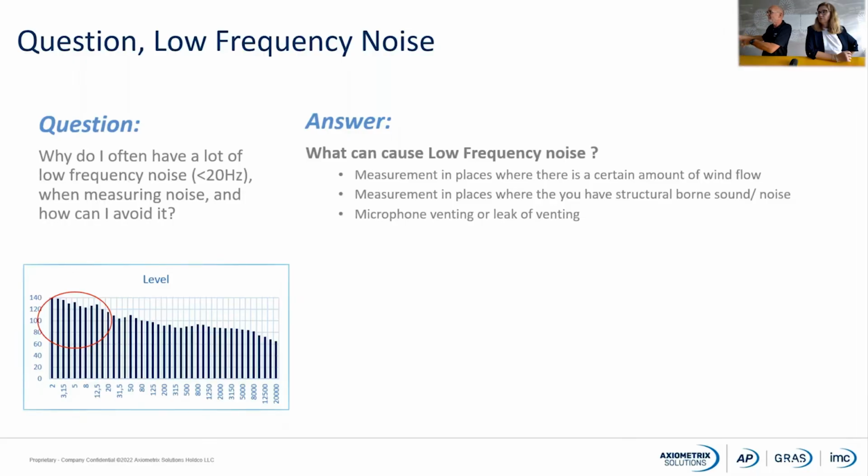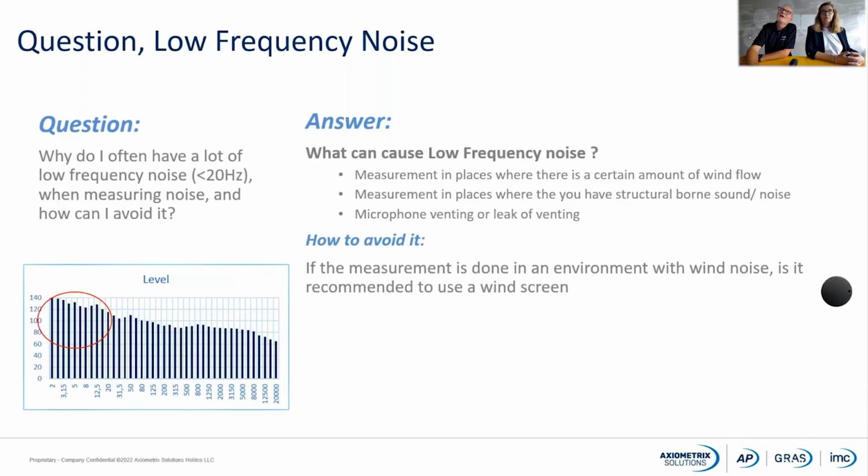It could be some vibration coming from the basement or whatever, creating this low frequency noise. Or it could also have something to do with the venting of the microphone. Maybe you have forgotten that there's a little venting hole on the preamplifier of the microphone, and maybe you have plugged this venting hole. Let's have a look at how to avoid it.